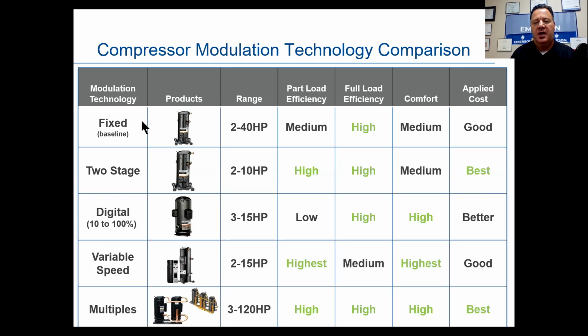Now, none of these compressors, with the exception of variable, have a pump for lubrication inside them. All right. So that's unique to that. If you're teaching scrolls, at least the Emerson scrolls, we do our lubrication basically by physics. We manipulate the shaft and different things in there and apply that lubrication up through that shaft by simply ramping up that 3,500 RPMs that a fixed scroll has. All right. Only exception to that will be our variable speed. It does have a pump in it.